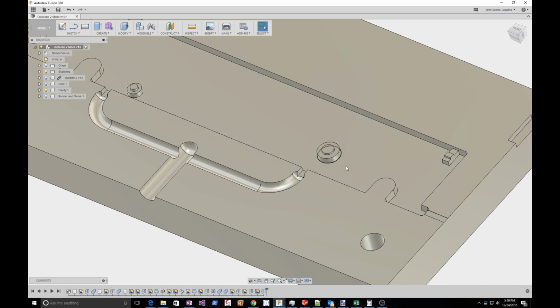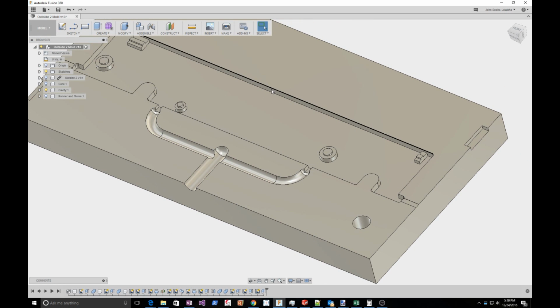As the plastic flows, it's going to flow toward the center and also flow toward the end, so we need to let the air out here. I may also have to add another vent up here and perhaps in some other places. It's easy to add additional air vents manually with just a few light passes after I've made the mold and when I find out where it's difficult for the plastic to flow.